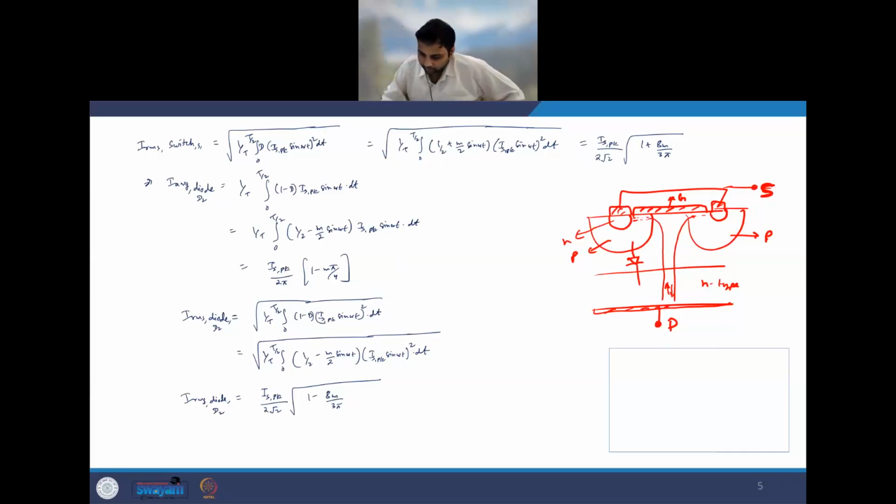So the moment you have the voltage across the MOSFET, I mean RDS on, if the current is going in this direction, RDS on of the channel which has been formed multiplied by the current which is going is less than the cutoff voltage of this body diode, then the diode will not turn on.